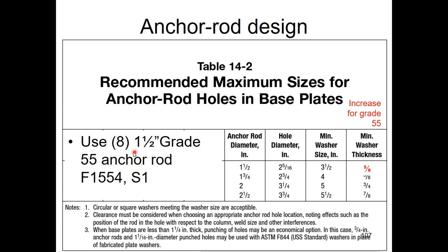So we're using 1.5" grade 55 rods. I always recommend using the supplement S1 that allows for welding of the material, so that gives us better options if the anchor rods are mislocated or damaged in construction.